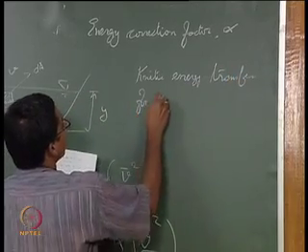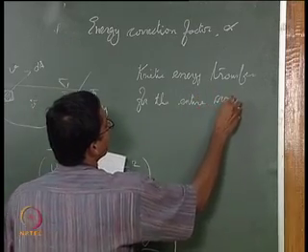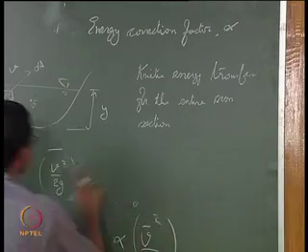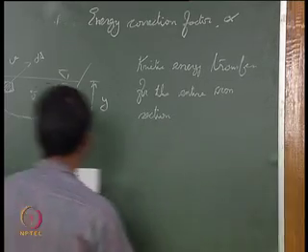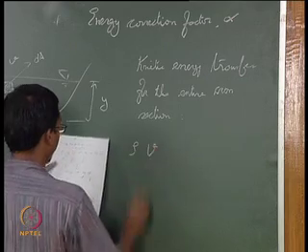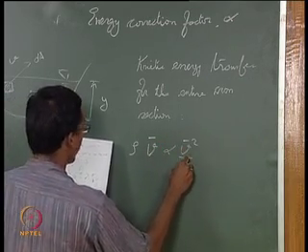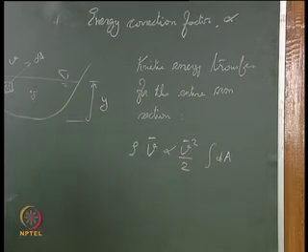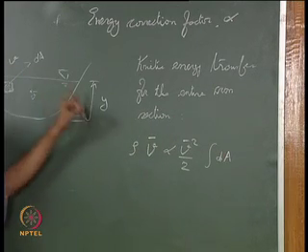Transfer for the entire cross section using both the approaches. So, this can be given as rho v bar alpha v bar squared by 2, using your average velocity. This is how you need to compute the kinetic energy transfer for the entire cross section.